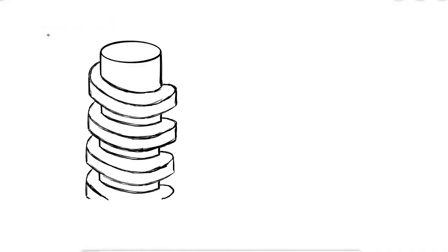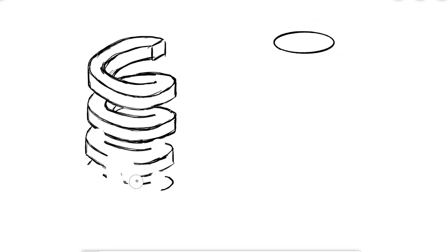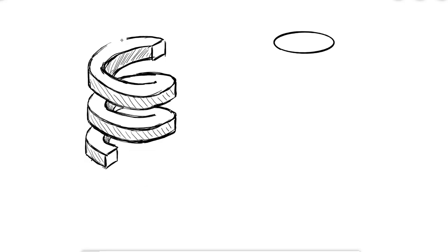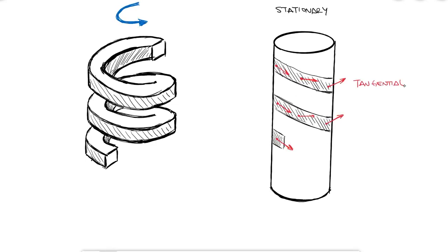Because the torque that goes into the screw is what overcomes the friction between the nut and the screw, and this friction has a direction that is opposite to the sliding between them, you could picture that the thread around the root of the screw is trying to slide around the stationary root, therefore causing a pure shear stress on the surface where the threads and the root meet.